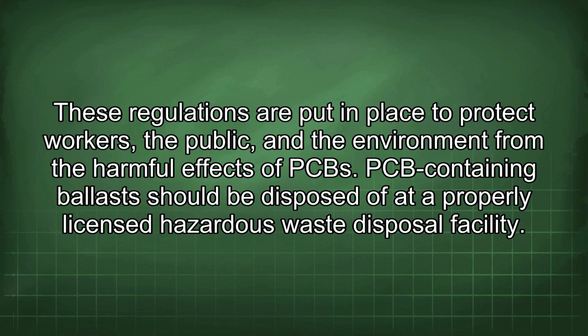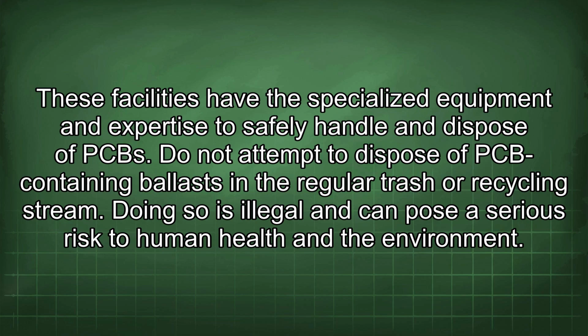PCB-containing ballast should be disposed of at a properly licensed hazardous waste disposal facility. These facilities have the specialized equipment and expertise to safely handle and dispose of PCB. Do not attempt to dispose of PCB-containing ballast in the regular trash or recycling stream. Doing so is illegal and can pose a serious risk to human health and the environment.